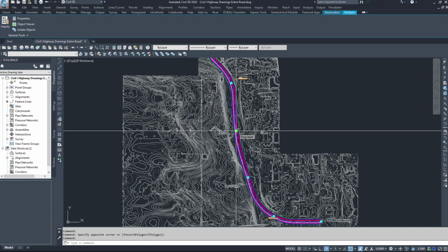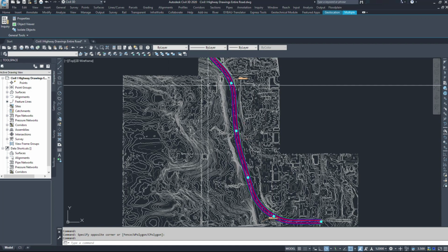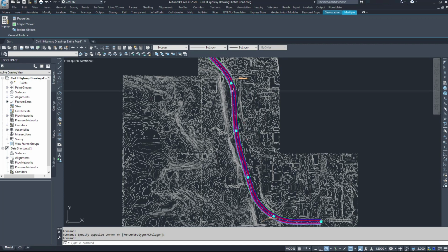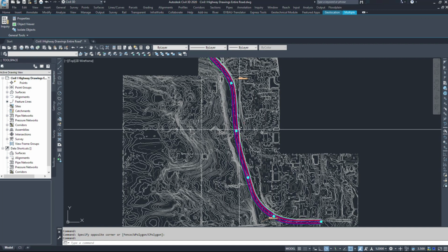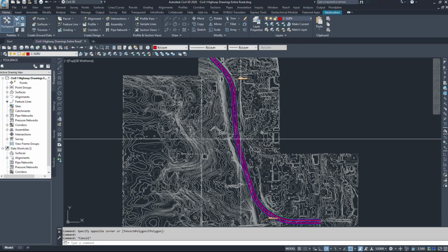However, it's just not the water that's on the road. Anything that flows downhill will eventually make its way into the ditches along the road, travel down the ditches to the low point, pass under the road and into our pond. So we need to worry about any land that is draining towards our road. Now with a hand survey, this is a little bit easier. There's less points, but we're using a LiDAR surface here.